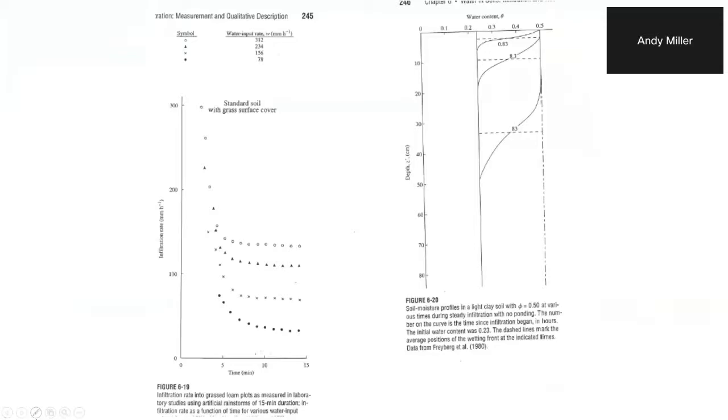Number one, the infiltration rates, these black dots, are for the lowest application rate. Now, the lowest application rate is 78 millimeters per hour. That's more than 3 inches per hour. That's pretty unusual. We do not get 3 inches per hour in an average year around here. We might get it every couple of years. So that's a very high rain rate, and these others are astronomical.